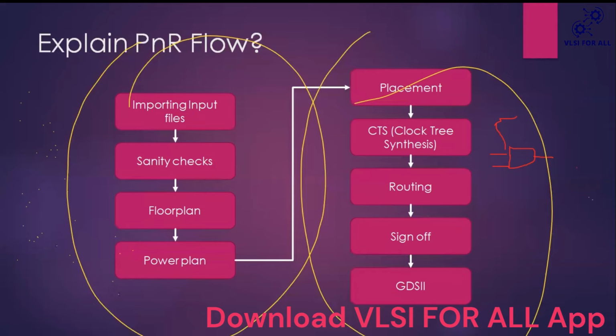During floor plan, what do we do? I'm talking about all of this at block level only. Top level is a bit different, but almost the same; there are some extra things we have to do. During floor plan, we create the core area and the core to IO boundary.